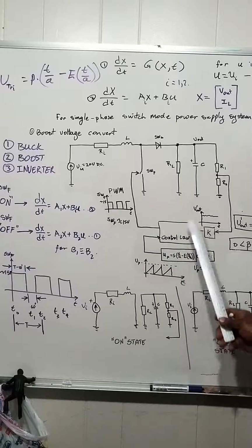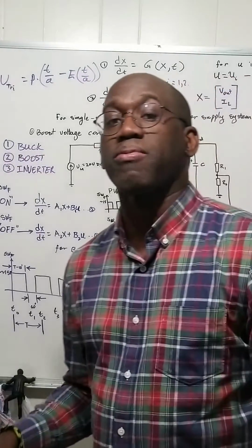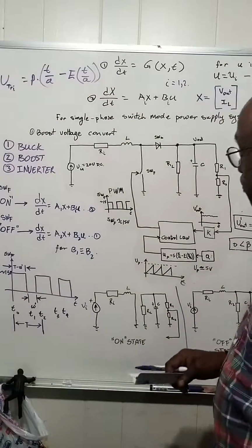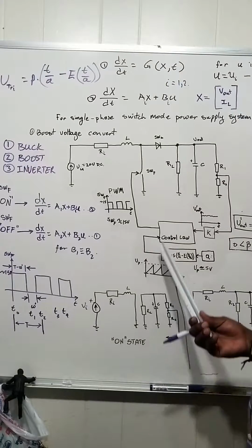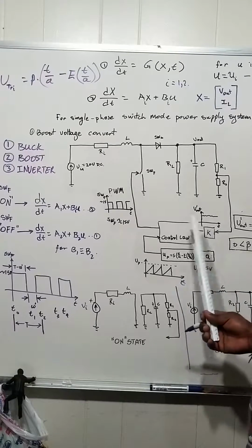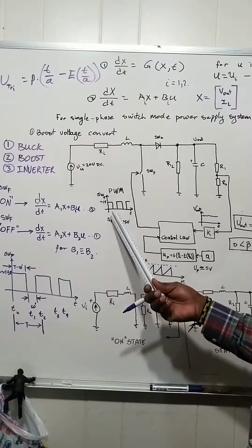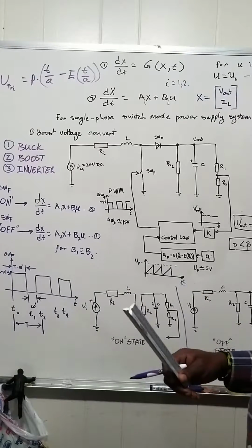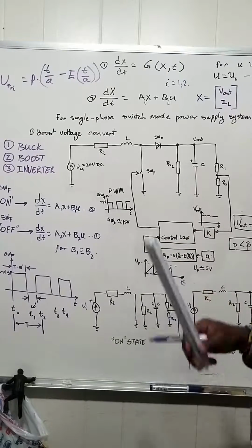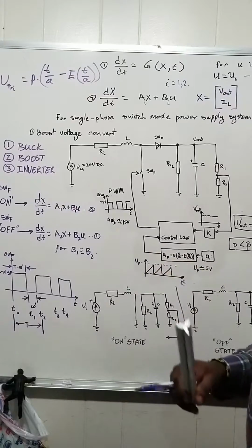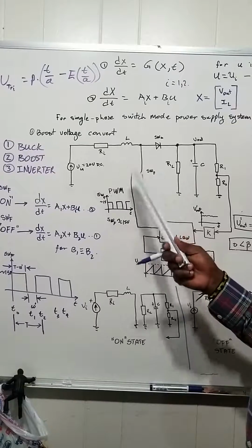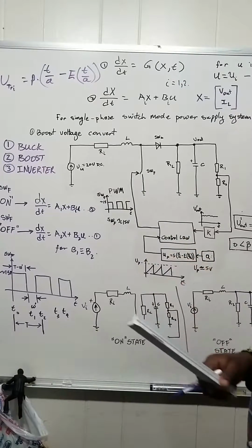right? And what is inside here are a set of operational amplifiers. They're the ones who actually, as a comparator, evaluate the difference between this signal and the feedback signal to give you this level of pulse. So wherever the feedback signal intersects with the triangular wave, the difference there gives us the pulse. And that pulse is what controls this transistor. And it switches on and off based upon the width that is given.